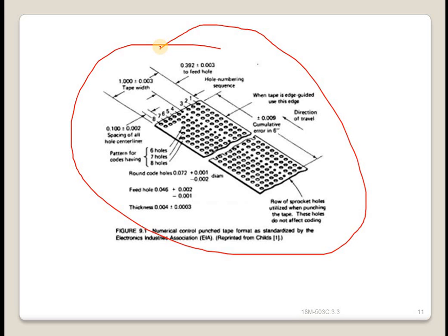Paper is often used for the initial preparation and testing of the part program. Then a production tape is duplicated out of one of the more durable materials for shop floor use. The punched paper tape is retained as the master copy. Holes are punched in the tape using a tape punch machine like a flexowriter. Tape preparation is accomplished either manually or using the computer.